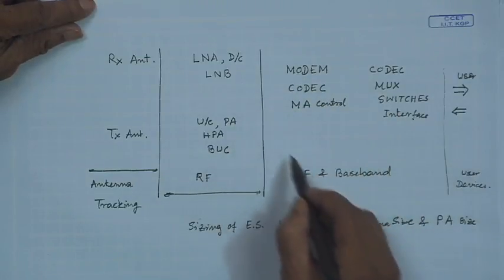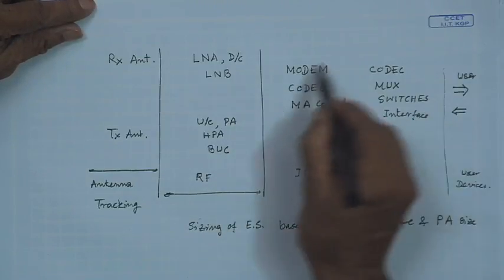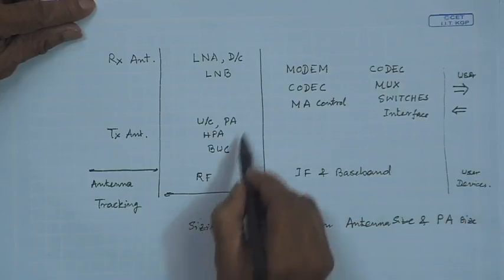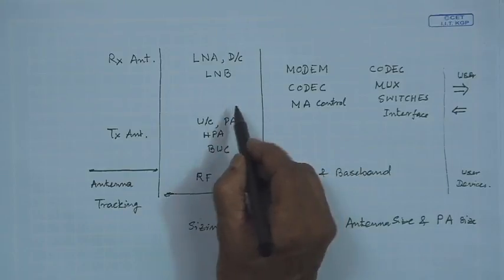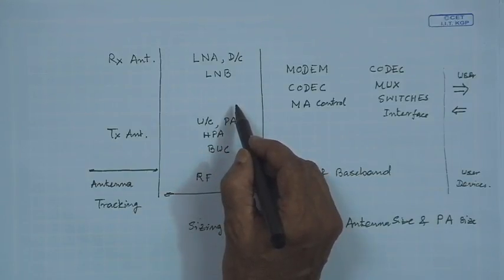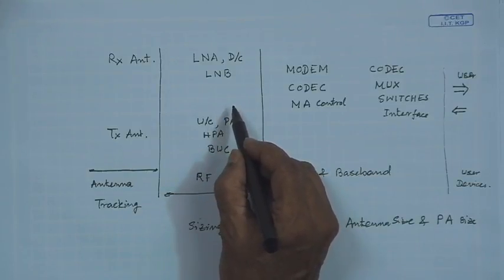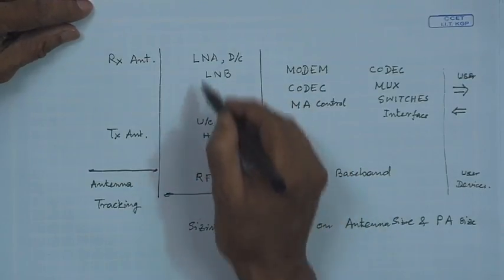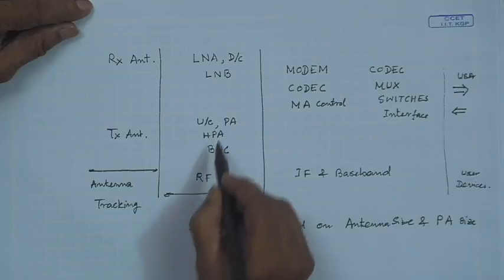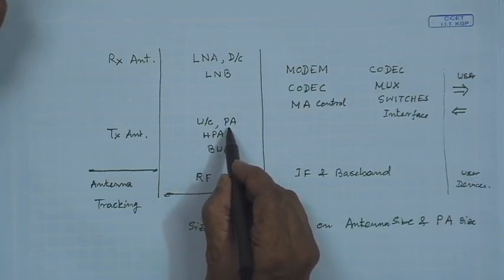But these are processor side. Using processors you can do all these things, and here the RF part you have to use separately. Nowadays RF ICs have started coming in, but for the timing, you can assume that they have separate transistors. In the power amplifier, sometimes higher power is required, then you go to tubes; TWTAs are used. And then the antenna.